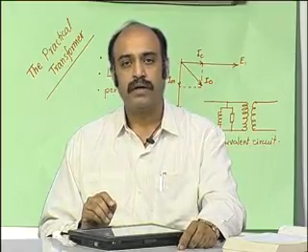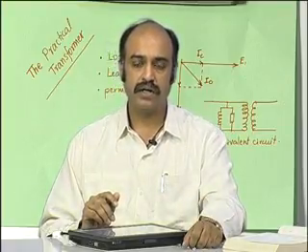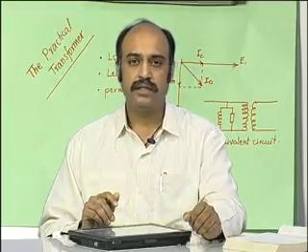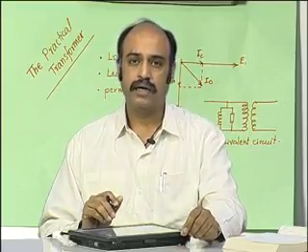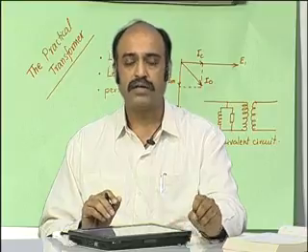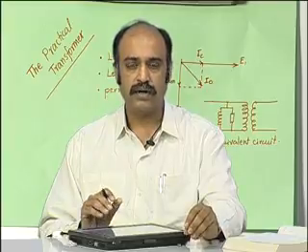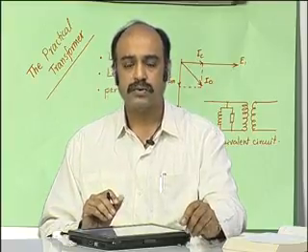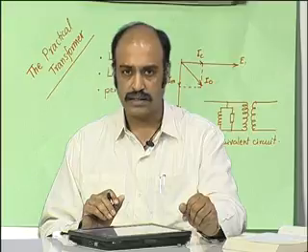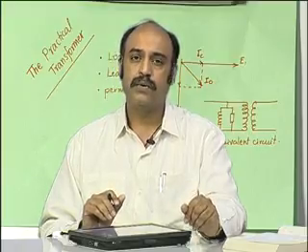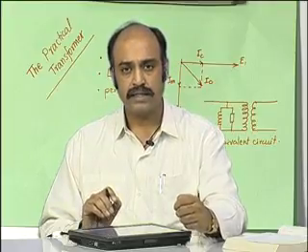in the core. Now, we saw that the practical transformer has all of these features which are finite, and therefore, there will exist core losses, and there will also exist a finite permeability, and because of this we included in the equivalent circuit of the ideal transformer 2 extra elements: one element called RC, which represents the core losses, another element called XM, which represents the magnetizing inductance, which means the current needed to magnetize the transformer.